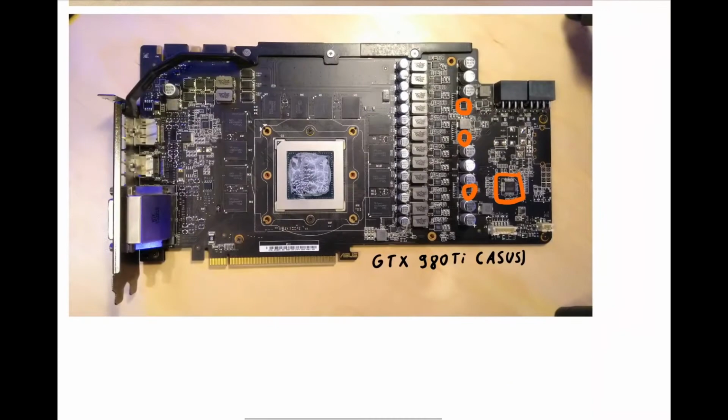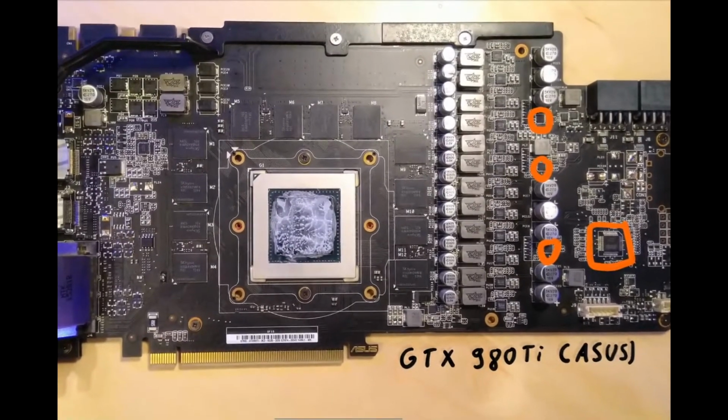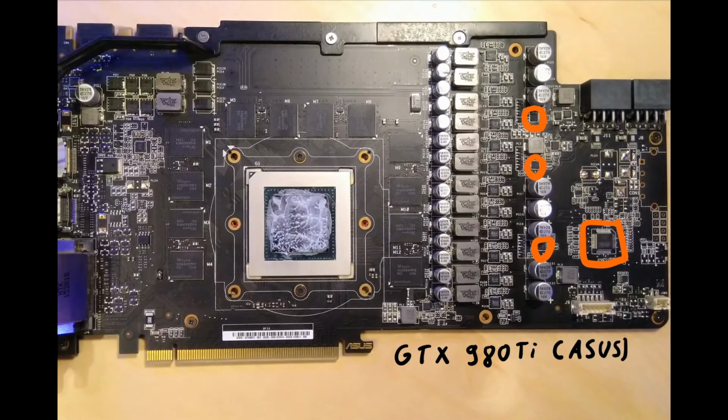And then for this controller right here, sadly you can't find the datasheet, but these doublers also have a name. They have a part number on them, and if you put these in, you will find out that they are doublers. I found the datasheet, and it was written there that they take 2 PWM signals and turn them into 4. So these are basically 2 doublers in one chip.